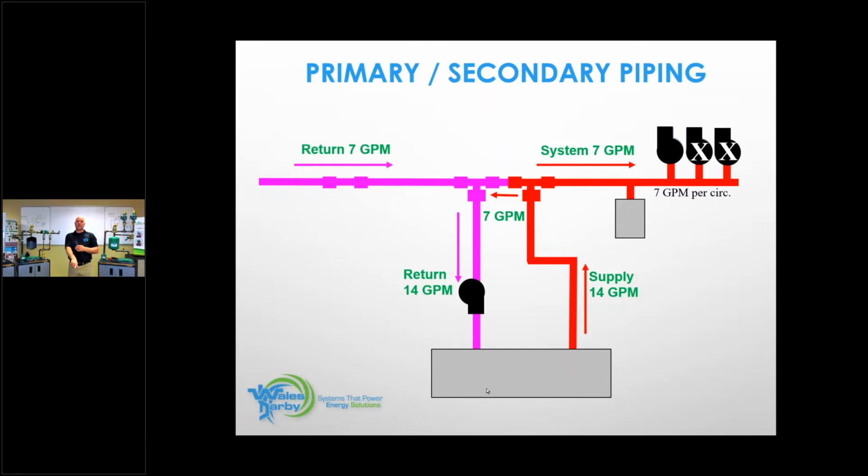I have a return water sensor that's gonna recognize that, and it's gonna tell my boiler input to reduce itself because my delta T of my heat exchanger is only 10 degrees. So the boiler has no idea how many heat circuits are calling. It only knows that the return water temperature is pretty warm and the water leaving the boiler is right on target. And it says, I'm pretty comfortable here. I can start to reduce the input. I'm still going to satisfy the demand that I'm currently receiving, right?